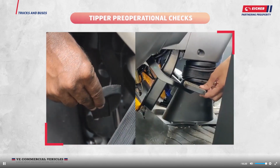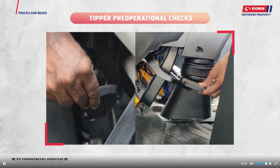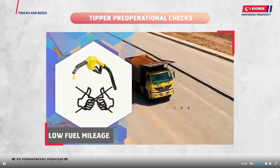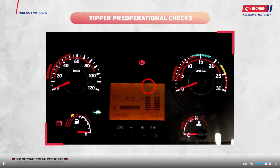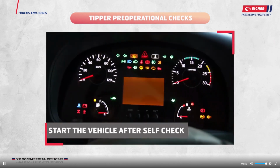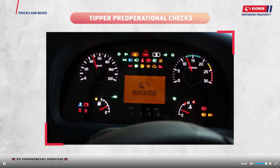Check brake and clutch pedal free play. It should be within 10 to 15 mm. In case no play, get it adjusted immediately to avoid brake overheating, low fuel mileage and poor pickup problems. Check all the gauges including the air filter restriction indication in the instrument cluster and then start the vehicle only after completion of instrument cluster lamps and gauges self-check.